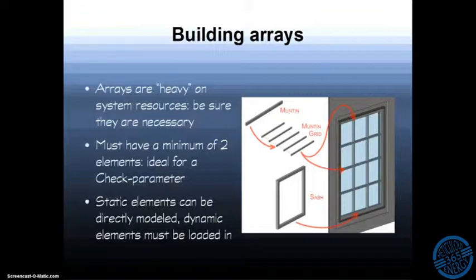That's not necessary. The arrays can affect your video card performance in the way you're moving around a model based on their joins and things like that, or they can affect your processor lag after a command, that you can hit a command and then wait 2 seconds and then it'll actually do what you asked it to. But by the time you're considering an array, you're pretty much sure that it's worth the trade-offs, so it's mostly just a reminder that the added functionality that you've decided you want does come with a cost. Don't be surprised if Revit slows down a little bit because you're putting arrays in a component that's going to show up 100 times throughout your model.